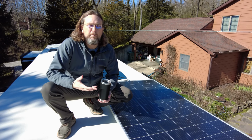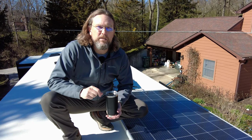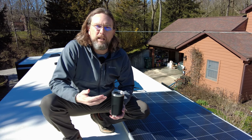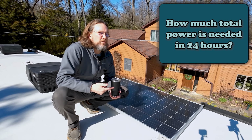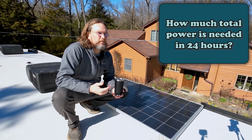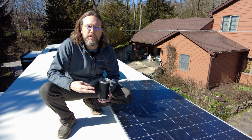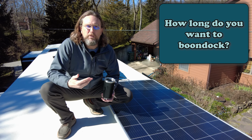So again, in my opinion, there are really three questions you need to take a deep dive into to determine how much solar power or how many batteries you need, or maybe even how big of a generator you need in your RV. And those questions are, number one, how much power do you need to produce in a 24-hour period when you're doing things like boondocking? Number two would be, what's the maximum power that you need to produce at any given time? And then the third question is, what kind of boondocker are you, or how long do you intend to boondock at a time?